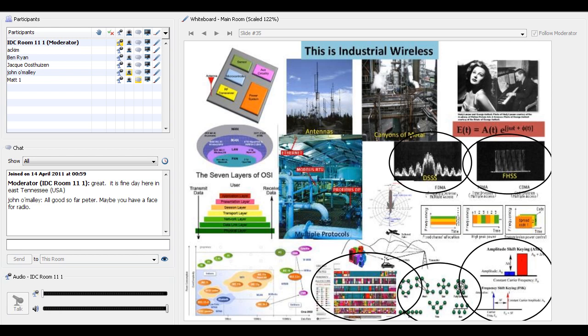Or maybe you want to stay at a constant amplitude, but you want to send a 0 at a certain frequency, and you want to send a 1 at another frequency. 0, 1, 0, 1. That is frequency shift keying, and that's how you can send your 0s and 1s with equal amplitude, but you're using frequency as the delineating factor between the 1s and 0s.